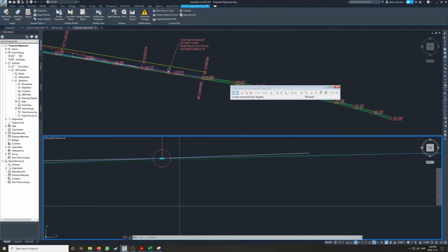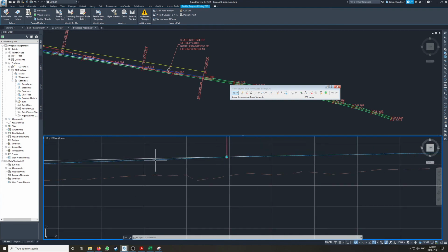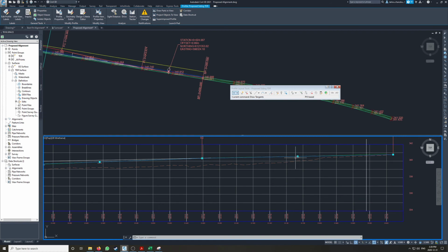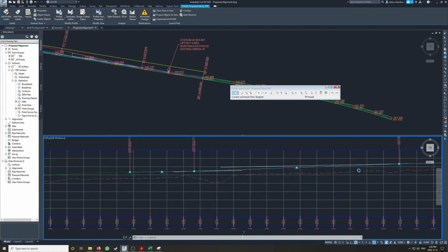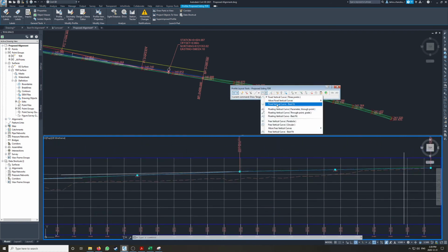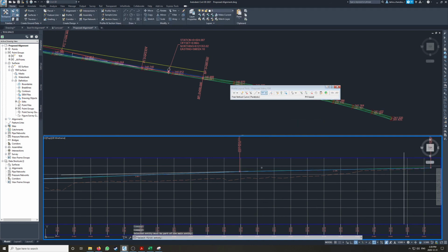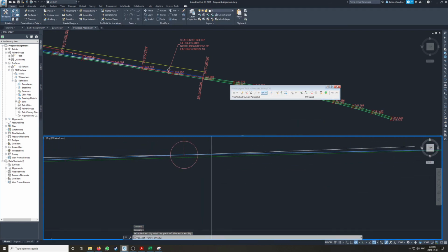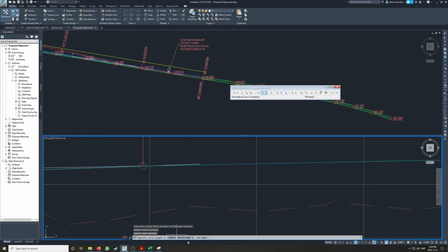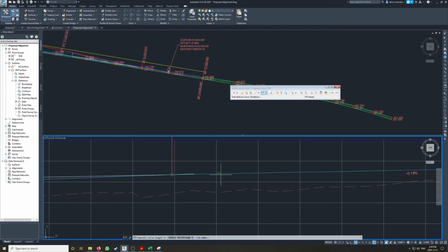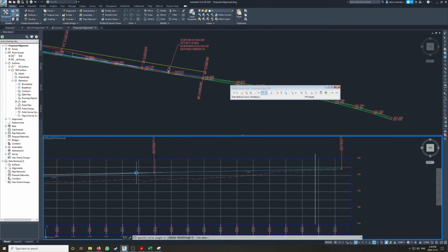So now we have two options. I like to enter in the vertical curve radius, or curve length, now. So we can do vertical curve parabola, and we'll set incoming, outgoing, and then for curve radius, you have to do a calculation based on your train speed to figure out your minimum vertical curve.